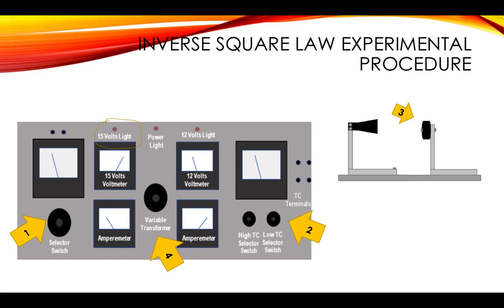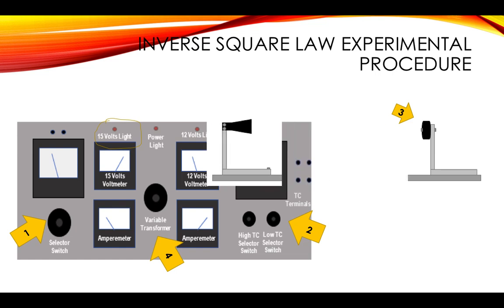The procedure was repeated 2 more times, changing the distance between the thermopile and the heater to 16 and 13 inches. In all these readings, the temperature had to remain constant. If the temperature varied, the run had to be repeated until the temperature remained constant during the readings.